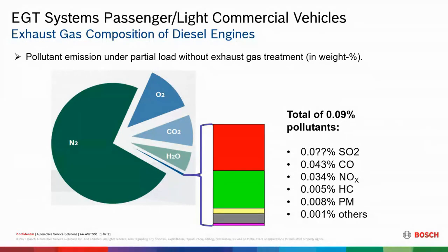So we took out the extra fuel that created particulate, and when we did that, we lowered the particulate amount, but we increased the combustion temperature. And when combustion temperatures go up above 1800 degrees, and you know, with a diesel, that's pretty easy to do normally, the oxygen mixing with the nitrogen of the N2 creates this NOx effect, which is really bad. It's carcinogenic to humans, and we've got to try to clean that up before we get out the tailpipe.